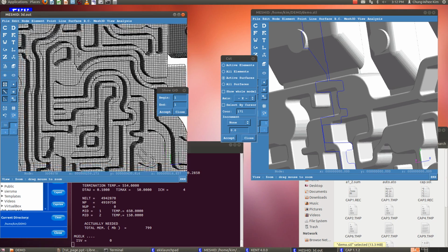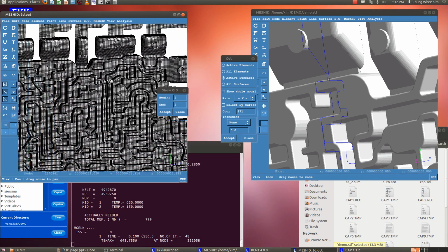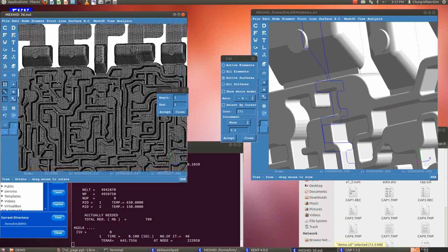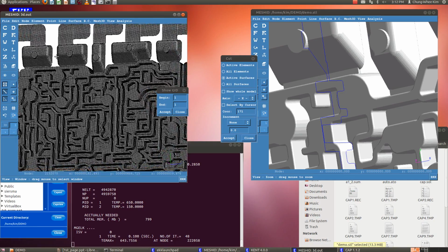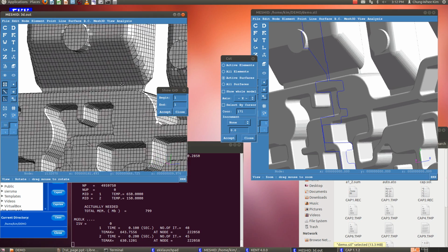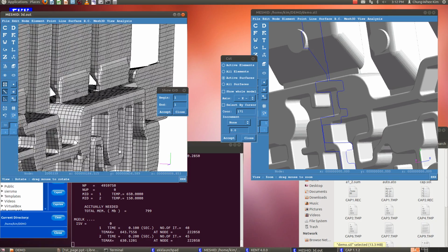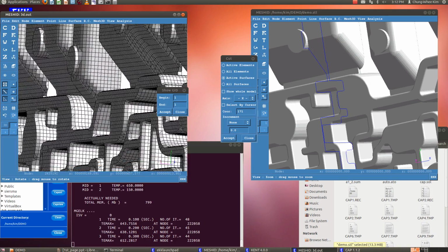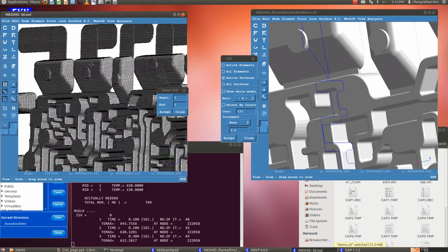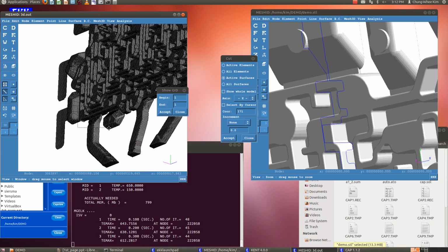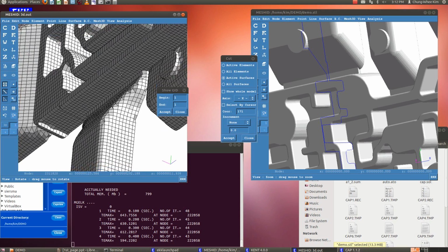All the channels are well defined. And you take a look at the overflows. Zoom into them and you see that they look very nice. There's no holes or anything in the gates. Turn it around to the back side, you see the pad there, it looks good. And the runners too. Let's go down and check them out as well. See, just like the overflows, they look really nice.